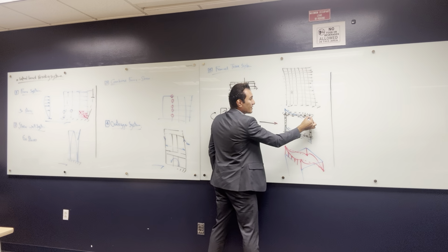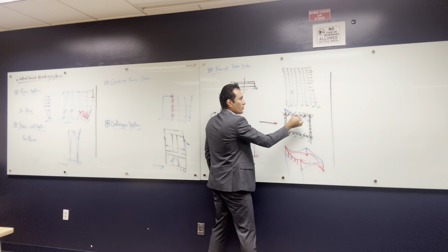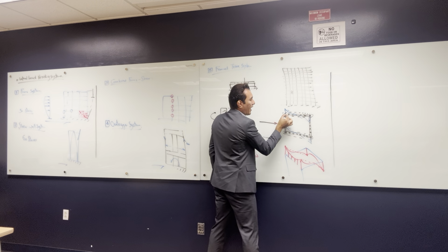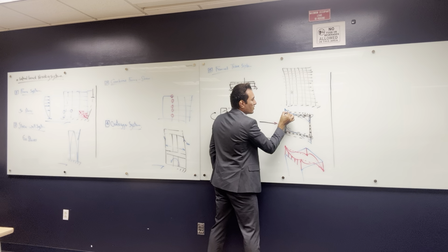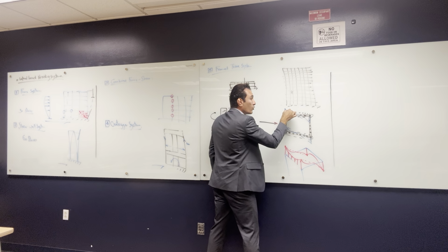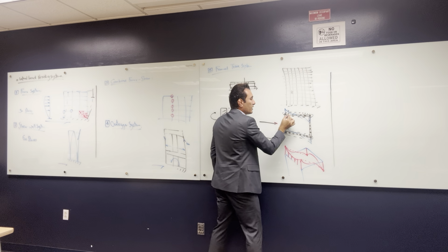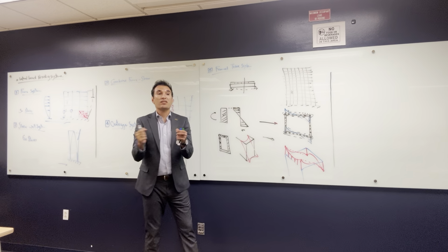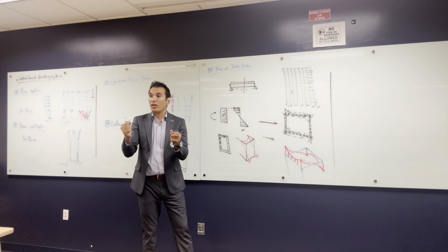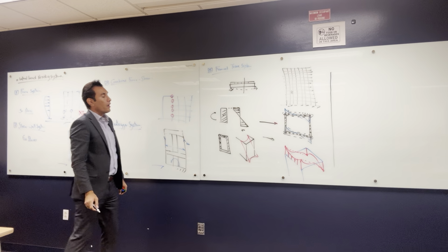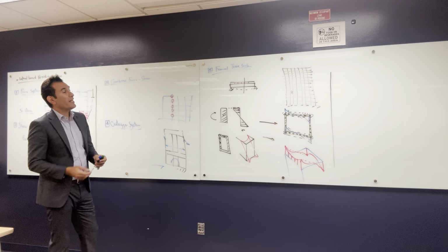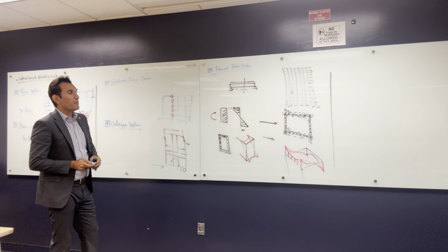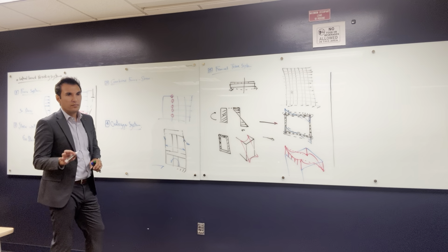But because this is not a solid shear wall, it happens that the stresses here don't reach this level. They only reach that level. And to bring it to the linear level, the beam between the two columns needs to be very, very stiff so that they can become linear. All right, so it's about the tube system, and the shear lag problem is a really, really huge problem.